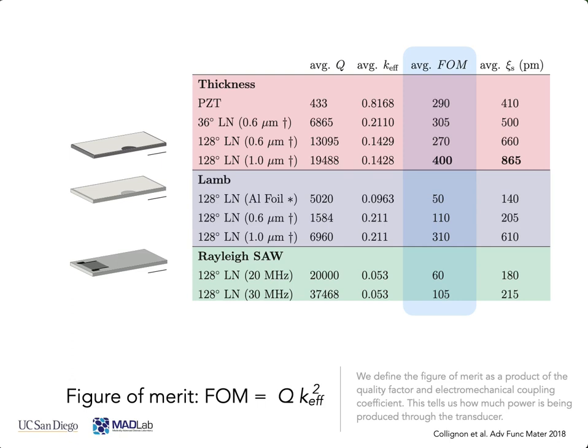There are also different kinds of vibration behaviors that you can obtain. There's the thickness mode, which is a rather traditional type of approach, where essentially the entire material is vibrating in thickness. It means it gets thicker and thinner with the application of an oscillating electric field. Those have been around a good long time, although the lithium niobate versions of them are relatively new. Lamb waves are similar to the Rayleigh wave. There's really very little difference between them, although Lamb waves are entirely through the material, and a Rayleigh surface acoustic wave is on one face of the material.